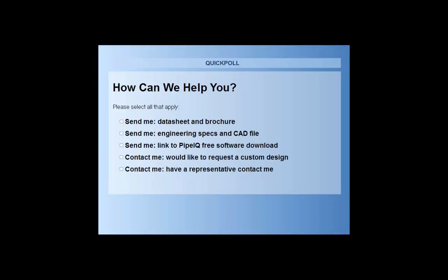If you're deploying FAAST in an application where, say, there's a process running and you know there's going to be elevated particulate level in the air, you have the option to decrease the sensitivity of the device during that time, and then have the sensitivity increase again when you know that process is going to be over. If you just want the device to be set to a static alarm level 24 hours a day, you would just set the obscurations for day, night, and weekend to the same level.